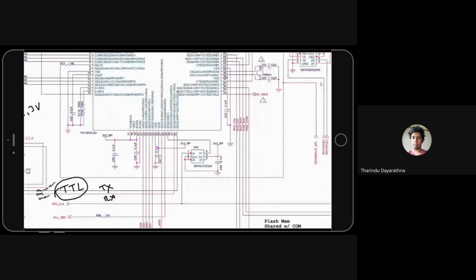And one more thing. So we have here the RTC clock line, that 32.768 hertz line, coming from near the reset pin. It goes to this buffer. From the buffer, it comes to this PIC.